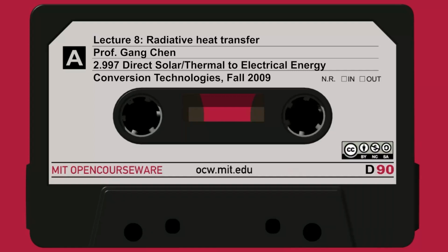So this is the absorptivity, and then selective is very important. Second law relation for emissivity and absorptivity. That's Kirchhoff's law. Okay? Kirchhoff's law says, at the same temperature of the object, the directional spectral emissivity equals the directional spectral absorptivity.